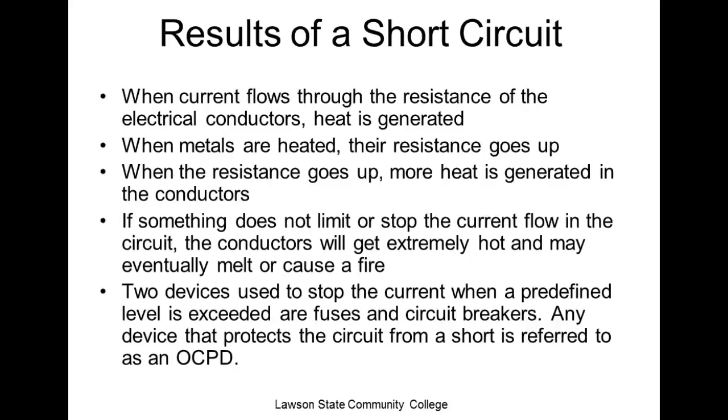When current flows through the resistance of an electrical conductor, heat is generated. When metals are heated, their resistance goes up. When resistance goes up, more heat is generated in the conductor. If something does not limit or stop the current flow in a circuit, the conductors will get extremely hot and may eventually melt and catch on fire. Or the source might catch on fire. Somebody's going to give up the ghost, right, on a short circuit.